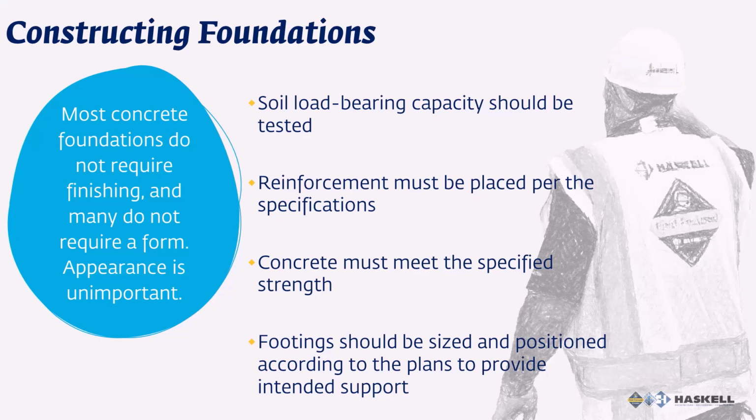Reinforcement must be placed per drawings and specifications. The concrete used must meet the specified strength, and the footing should be accurately sized and positioned to provide the intended support. Concrete can be cast directly against the earth as long as no standing water is present during placement.